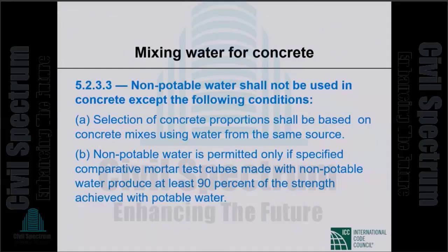This is the important part. BNBC 2020 does not cite a specification or standard for mixing water, but it very importantly has this section, 5.2.3.3, titled non-potable water, which shall not be used in concrete except under the following conditions.